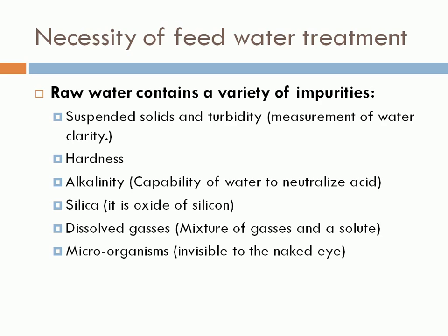See, feed water is an essential part of a boiler, right? The feed water is put into the steam drum from a feed pump. In the steam drum, the feed water is then turned into steam from the heat, right? After the steam is used, it is dumped to the main condenser. From the condenser, it is pumped to the deaerated feed tank, and from this tank it goes back to the steam drum.